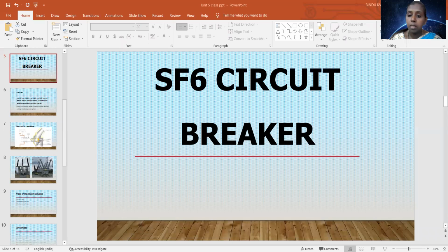The medium in which the arc extinguishing takes place influences the characteristics and also the lifetime of the circuit breaker. If you are going for a vacuum circuit breaker, it is restricted to a system voltage below 38 kV. Because of the characteristics of the vacuum medium and also the cost, it is not suitable for voltage ranges exceeding 38 kV.